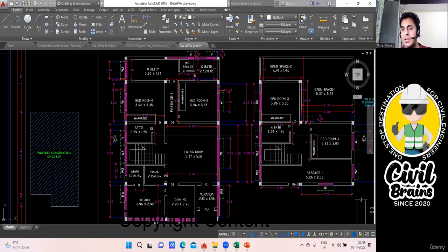Again, say this is the door part. There we had deducted the door part, and for the door part no sill concrete will come, so you don't have to calculate this. That means this 3.89 that you added in that perimeter, you need to deduct it. That's it. This part will come, and this part will come. This much you understood? Fine. So that is why I only took care of the external part.